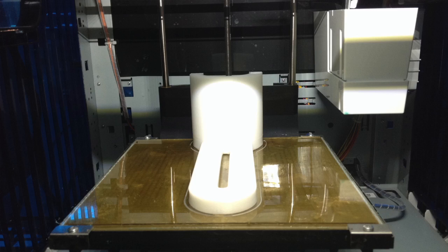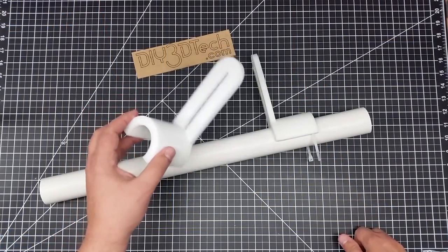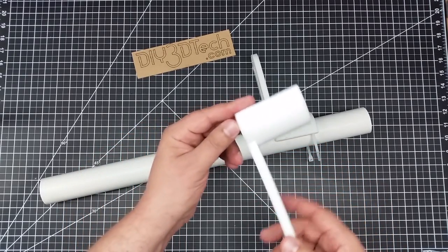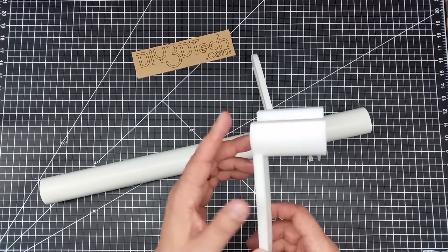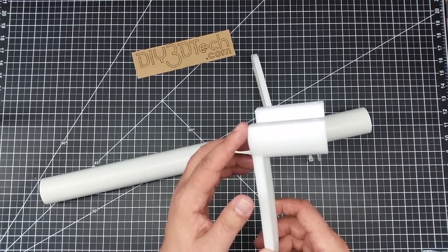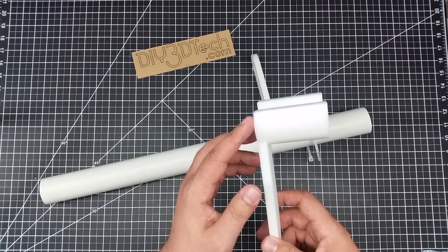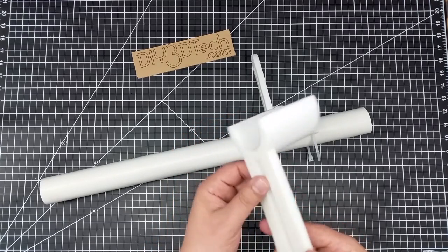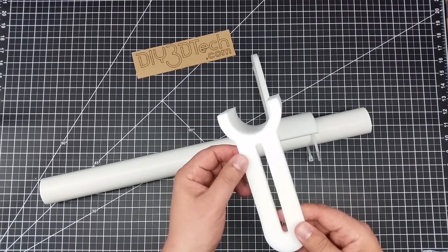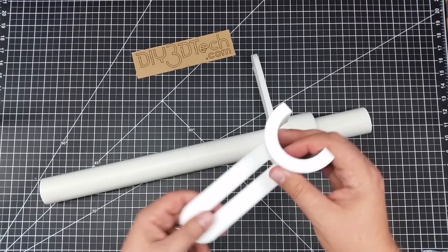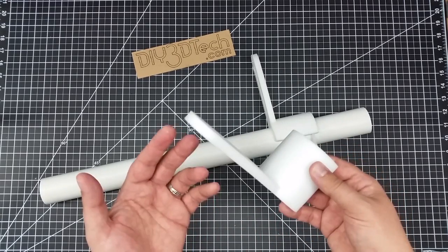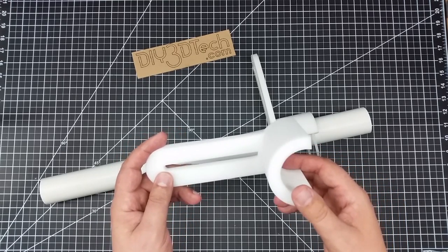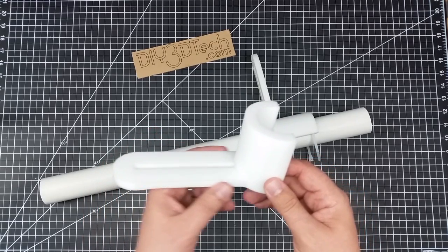Now, back to talking about this a little bit. I printed this and I had to go up to 110C on the bed. I did get a little bit of warping on this back edge, and as you saw from the print on the bed, this was at the very back of the bed, on the cooler part. The pieces more towards the center were pretty good. I printed this on PEI substrate, so it came out really good. Knock on wood, held good too. Printed the filament at about 245C.